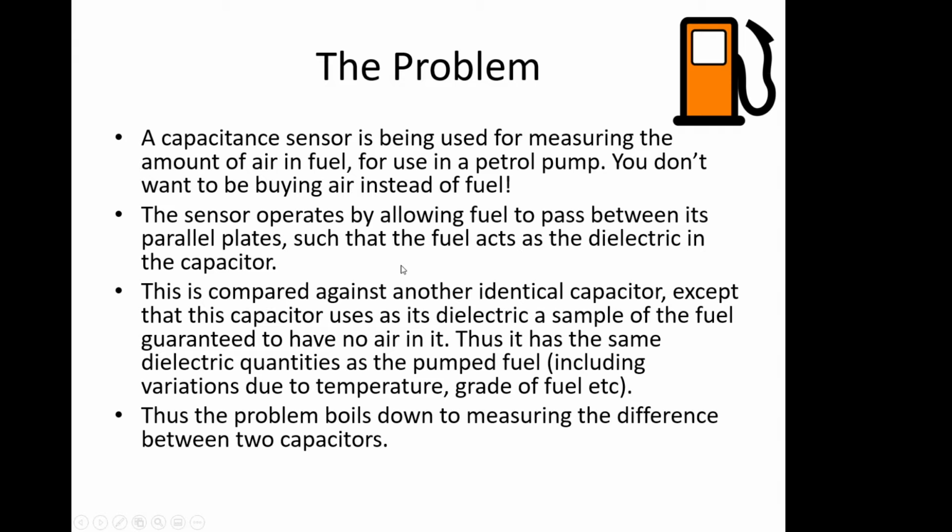One of the ways we could do it is with capacitance, because we can make the fuel act as a dielectric between two plates of a capacitor, and if you've got air as a dielectric, you'll get a different capacitance compared to when you've got fuel as a dielectric. This only works because fuel is non-conductive. But that's what I'm saying. Know your enemy, and then you can start to define what will work and what can't work. And then when you've got a list of things that will work, you can choose the one that's the best.